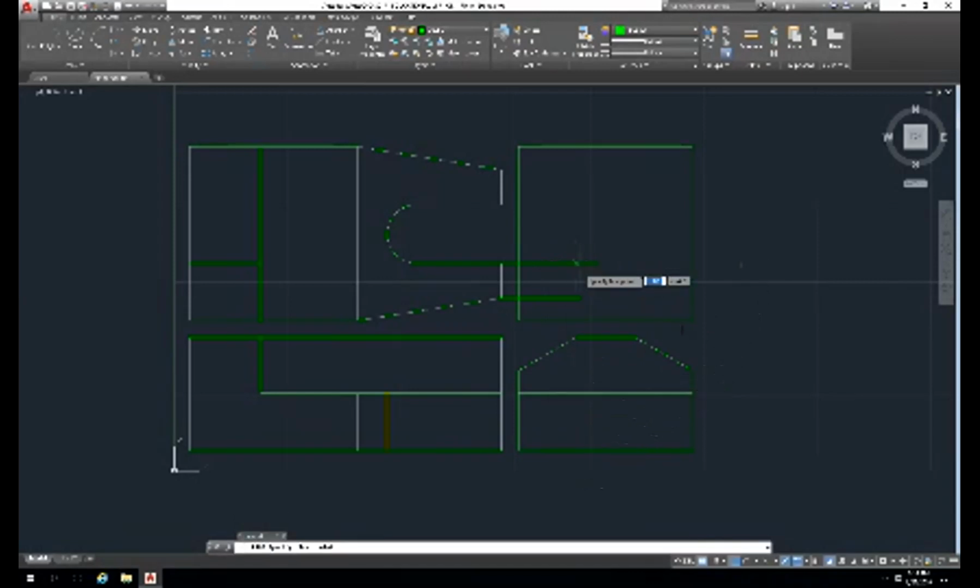Whoops, what happened? Oh, I didn't click with the mouse. Click, move, click, enter, space bar, click, move, click, space bar. Enter, space bar, click, move, click. See, that's the whole thing, is that you don't drag in AutoCAD. You click and you move. You drag objects around, and when you do 3D, you rotate the cube to get the objects to rotate, but you don't.